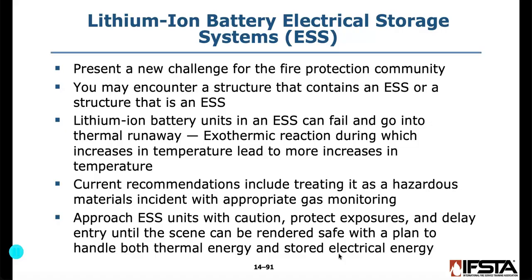Approach ESS units with caution, protect exposures, delay entry until the scene can be rendered safe with a plan to handle both thermal energy and stored electrical energy. So you may not know that what you have is an energy storage system fire. You'll know if it's a building that's all energy storage system, and then that building's on fire. But if you go to a home that has a garage fire, you may not know that there's an EV in there that's charging and they have a battery pack in that garage. Okay, you might not know that, so that it stores energy there. So you want to be very cognizant of that.